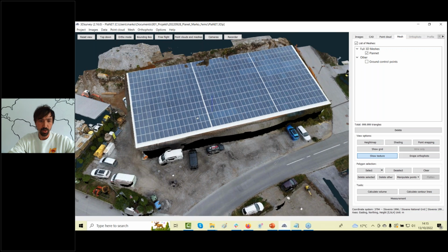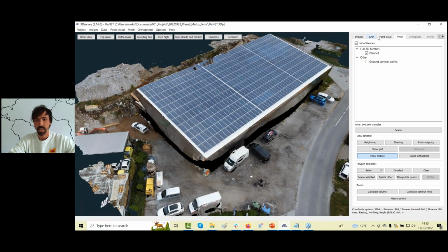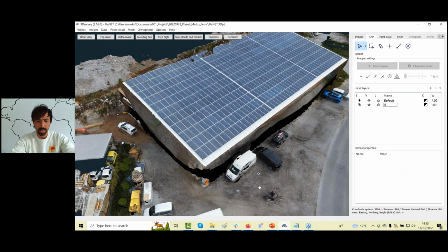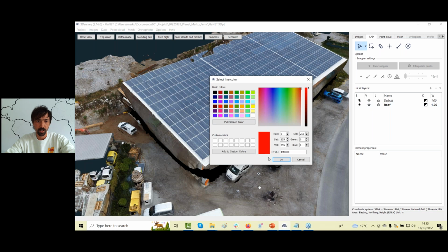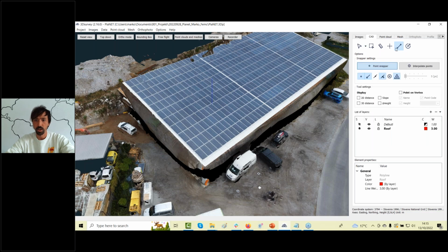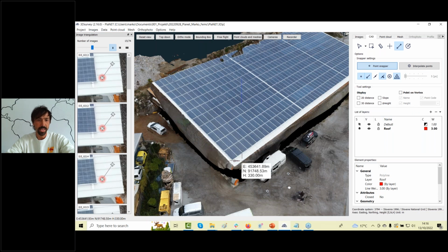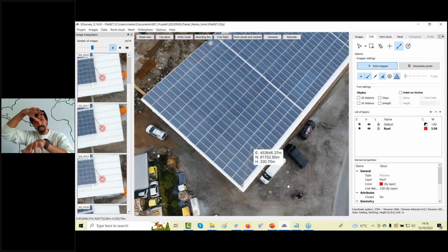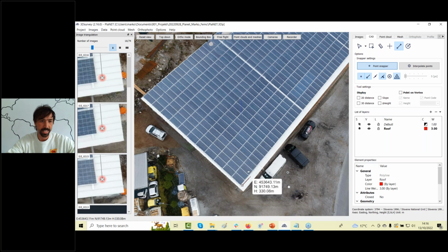And then the main point of this first presentation is when you go to CAD, and you can create a new layer. So let's say roof. I will make this layer active, set the red color so it will be nicely visible, and thickness to 3. Now when I go to the line drawing tool and snap on the roof, I immediately get on the left side a new window with all images which are available for this vertex position. You can see the images are sorted immediately based on the perspective you are viewing, so it's super nicely designed.